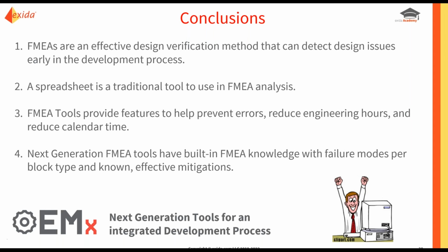A spreadsheet is a common traditional tool for use in FMEA analysis and will absolutely work. My recommendation is to keep the FMEA spreadsheet as simple as possible and eliminate any columns that aren't absolutely necessary to achieve your objectives.